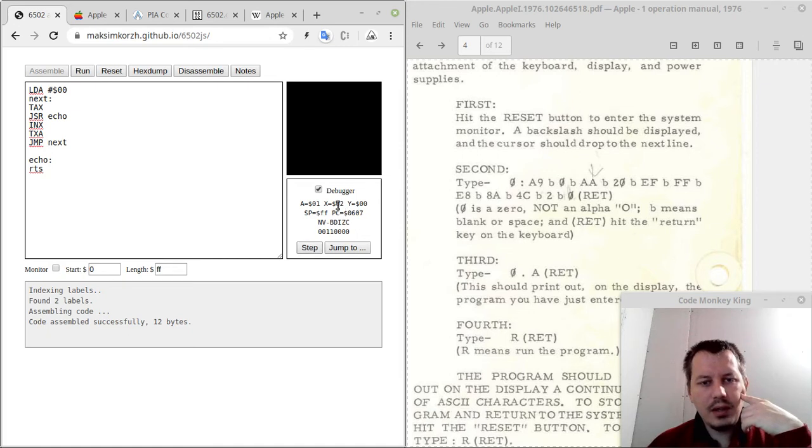Okay, and then it increments X again, transfers it back to A, and this is the way we can increment the A register many times until it reaches the value of FF, I believe, right? And then it just wraps around and becomes 0. So if we just run this, you see the A register wraps around, and this negative bit is blinking. That's because when the most significant bit gets set, the negative flag gets affected. So it's pretty natural, right? So we just loop around over the values from 0 to FF in the A register.